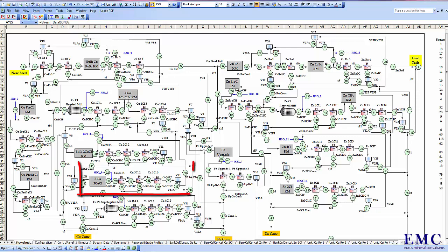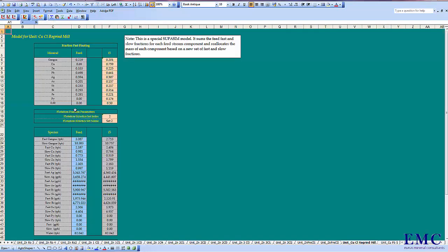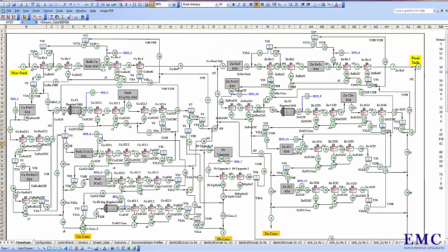On the third stage of cleaners, you can route that either directly to final concentrate or put that through a regrind mill, and that concentrate can go to the copper concentrate. The tailings can be rerouted, as you can see, into a further lead upgrading. There's a facility where, for instance, in these regrind mills, if I click on these, at the moment that has a regrind mill program in it, but that can be reset so that it becomes effectively a mixer.